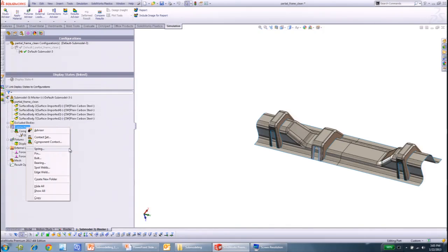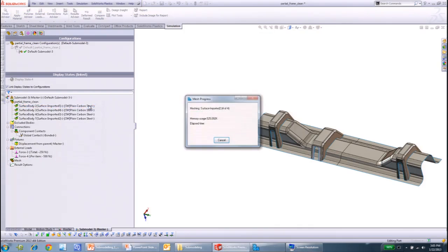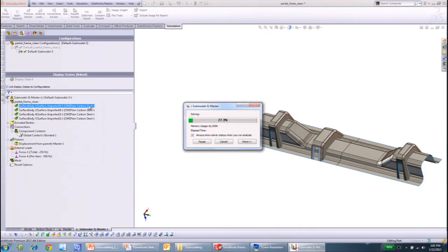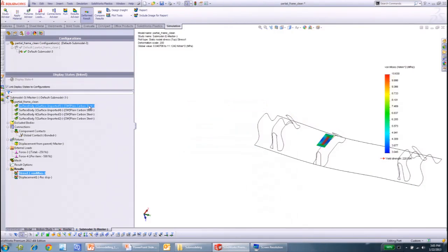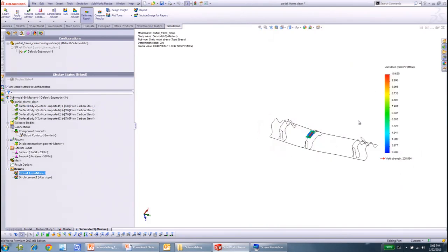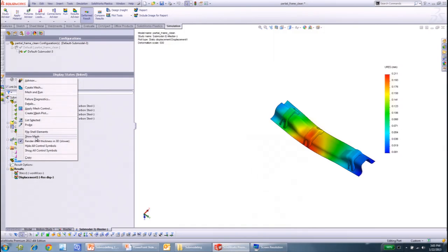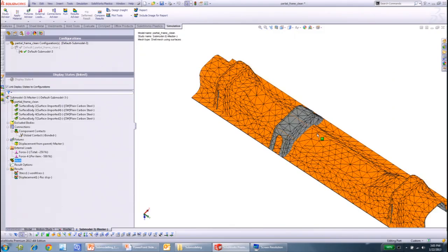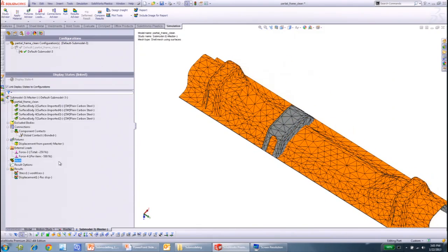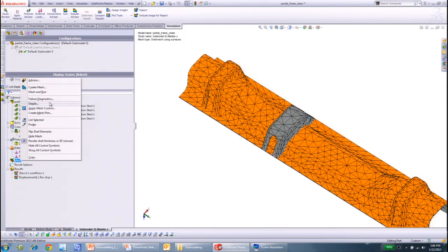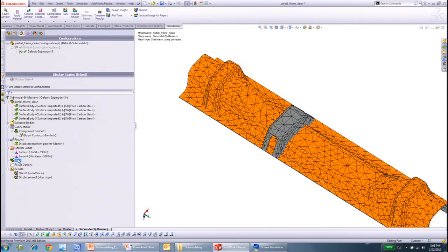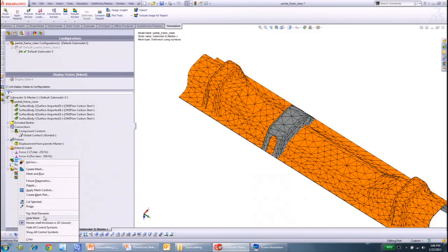So you can refine a few things, and obviously you can refine the mesh as well. You can make it finer. If you just run it as is, it will take whatever settings you had at the parent and use the same settings for the submodel for mesh and everything else. So you're going to get very similar results. If you look at the mesh, it's going to be very coarse. But you can go back here and apply mesh controls on areas of interest.